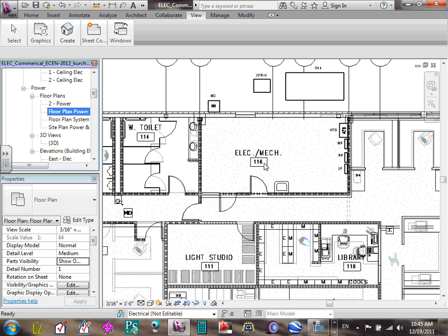To do the riser in Revit, there's two ways. The poor man's way, which we're going to do, and you guys can modify it to the rich man way. All these panels that we put in the wall, I'm going to put a section and make the section look at them. If I make a vertical section looking at the panels, and I grab this section and put it in a view, you're basically looking at what you can see on the wall. Since they're in two different locations, I can't put one section that captures all of them. I'm going to create a few sections.